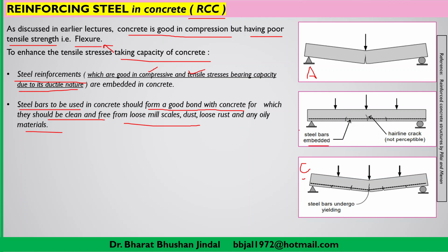And after that, the steel bar as well as the concrete will act as a composite material, not as individual materials. Suitable treatment may be adopted to get the reinforcement clean. You can use sandpaper, and if any scales or dust is seen on the steel, you can clean the reinforcement with sandpaper before embedding it in the concrete.